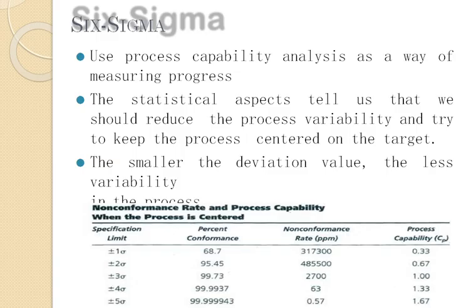For plus 4 sigma, plus 5 sigma, plus 6 sigma, you can see in decimals how the percentage conformance extends. So if you go to 6 sigma, you can see the non-conformance rate is very low. That's why the majority of companies go to the 6 sigma limit, so that the percentage conformance is higher and the overall output is good.